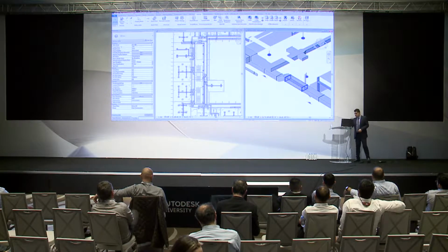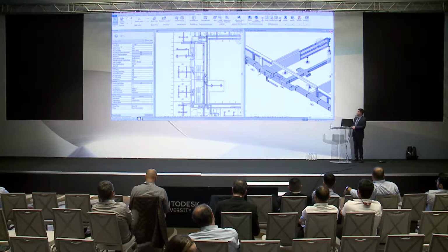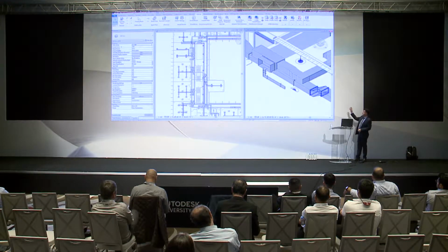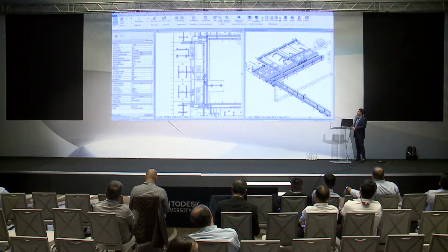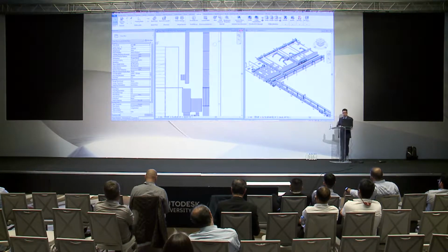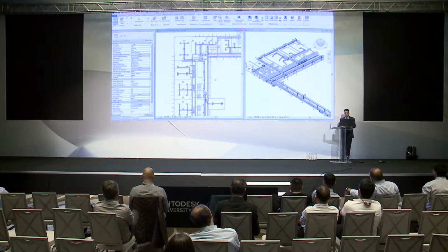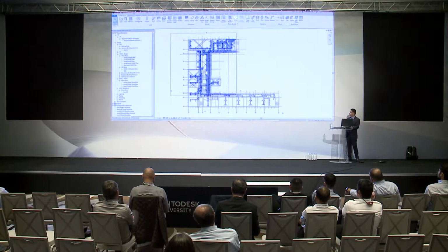And once that is done, the next portion is we're going to convert it. After the conversion happens for all the fittings and all that, if I need to, I can go and place the hangers as well to add a little bit more detail. And once that is done, you can see here I have my connection details on the left-hand side. You can see I have those cuts. If it is slip joint or if it is flanged, I will get the flanges automatically.